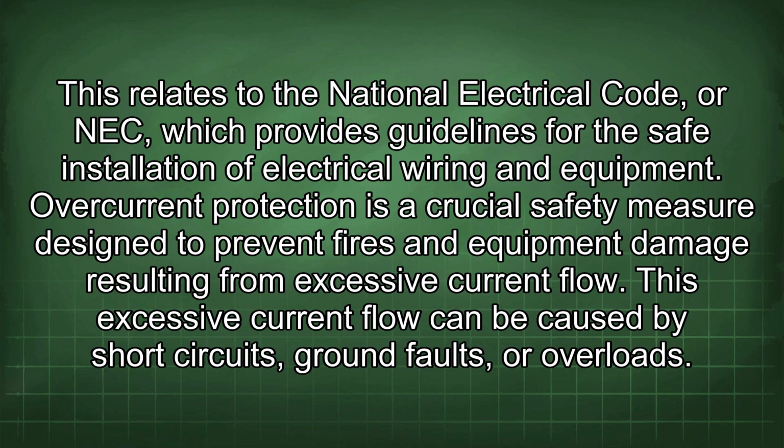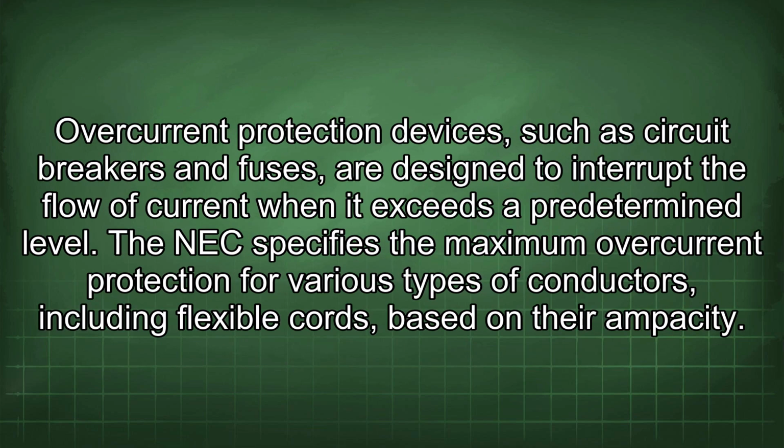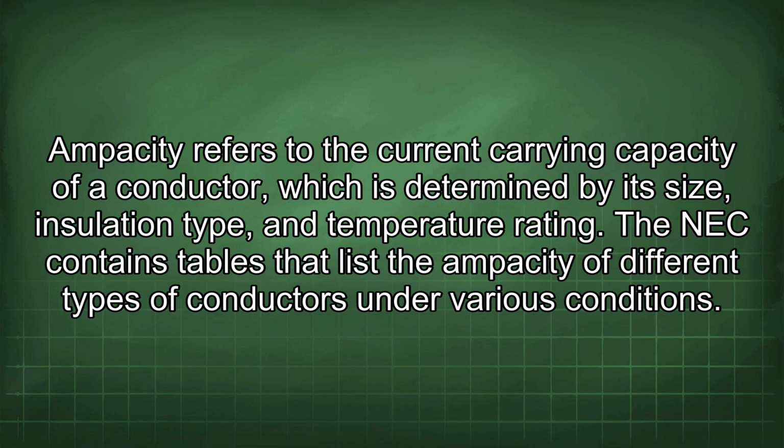This excessive current flow can be caused by short circuits, ground faults, or overloads. Overcurrent protection devices, such as circuit breakers and fuses, are designed to interrupt the flow of current when it exceeds a predetermined level. The NEC specifies the maximum overcurrent protection for various types of conductors, including flexible cords, based on their ampacity. Ampacity refers to the current carrying capacity of a conductor, which is determined by its size, insulation type,